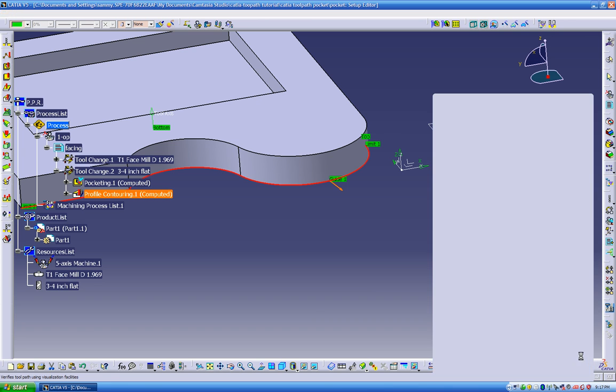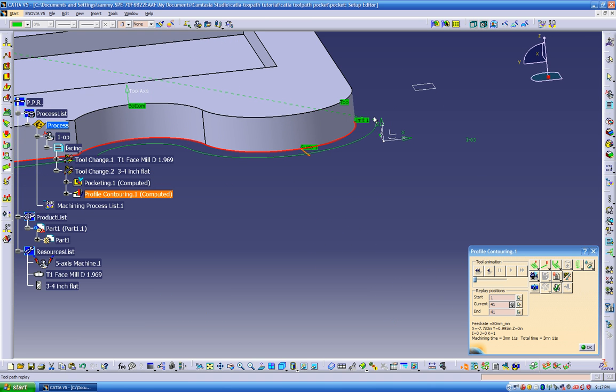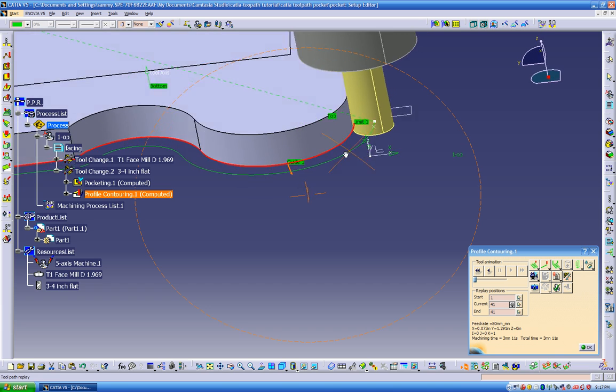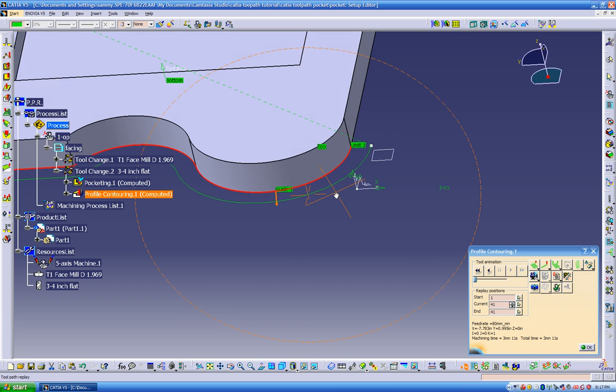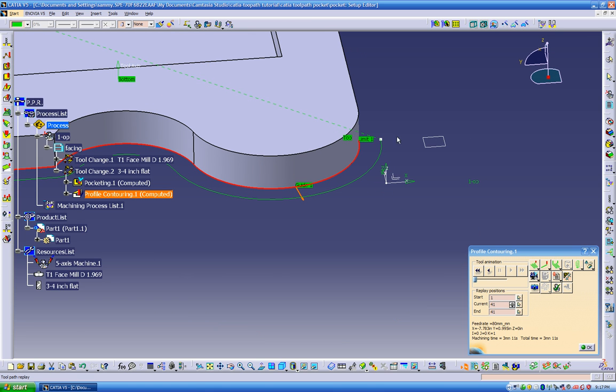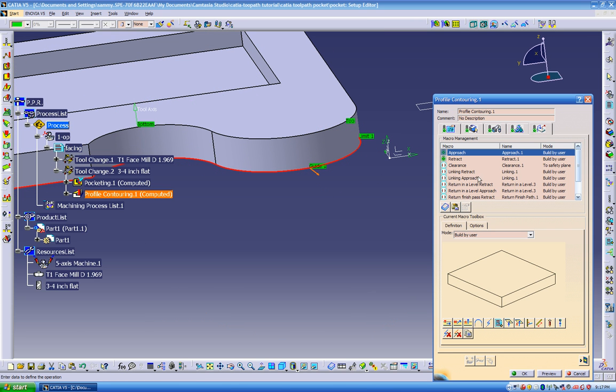Let's do toolpath replay. So as you see, the tool starts right here at the bottom, right into the part, which is not recommended. It's gonna make a big mark into the part. So that's why I always have to lead in and lead out. Start outside, come back very nicely, and the part is gonna give a nice finish. So that's why I added the circular motion.